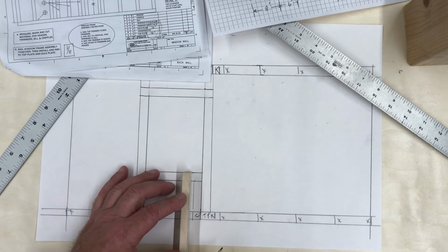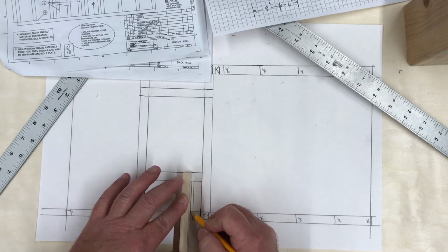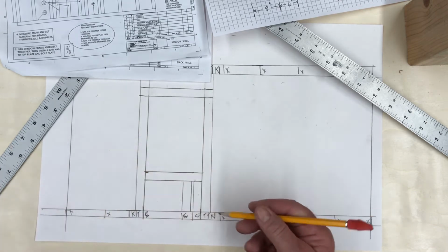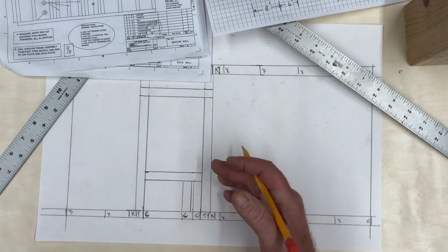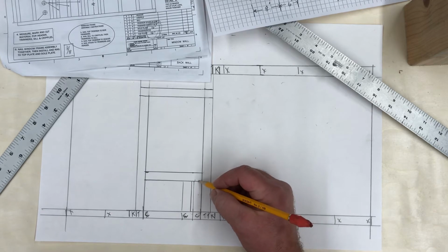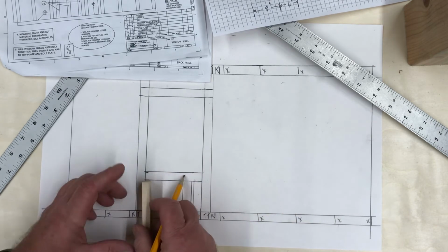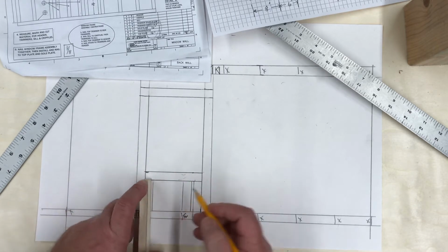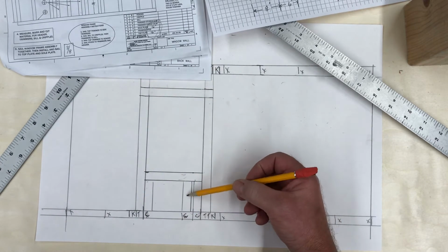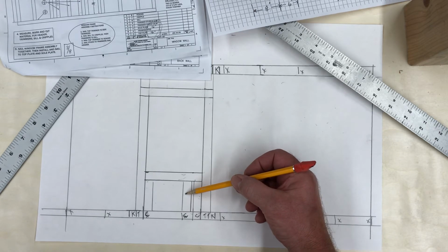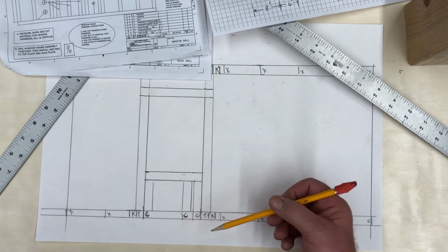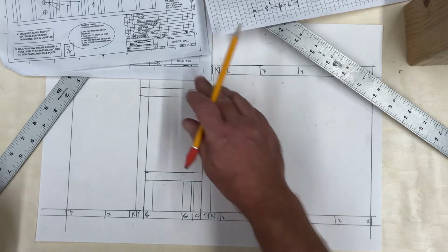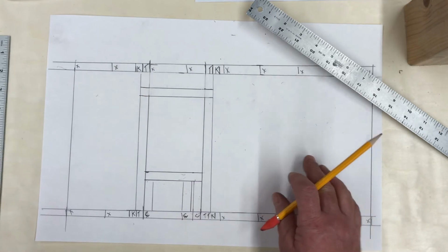Now if you notice right here, my cripple stud is pretty darn close to the other cripple stud. That's fine, because that's just the way it works out in our design. We need one on the end here, and we also need one on the end right here. So we have these 2 mandatory. This one falls in place due to the line being 16 inches on center, so we still need to put that one in there. Now, what's left in our wall?